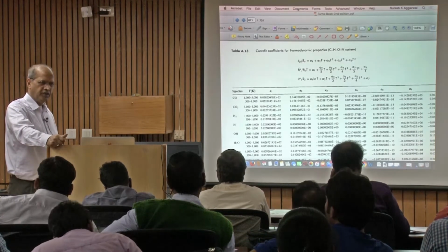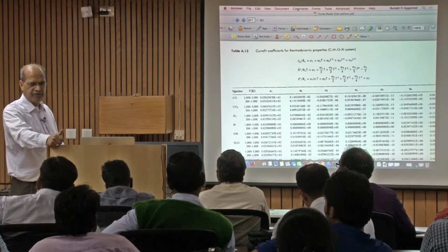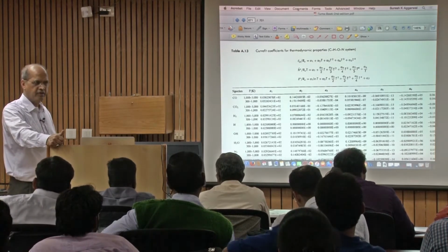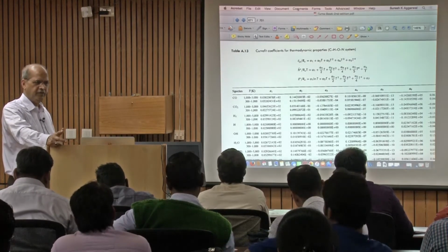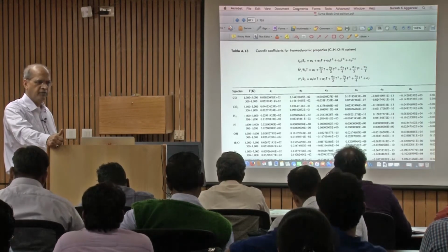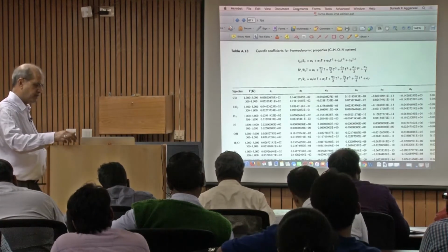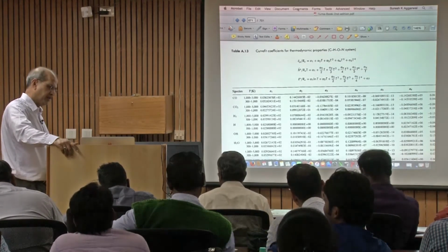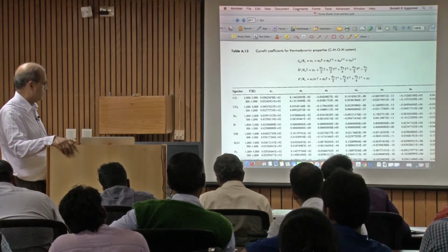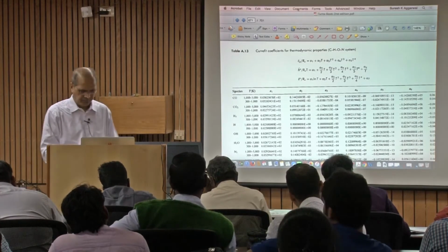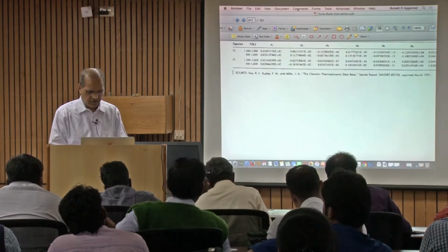For flames, you also need the transport data, like diffusivity as a function of pressure and temperature for different species, viscosity, and thermal conductivity. So you provide 3 files: kinetic file, thermofile, and transport file. If I can find some sample case, I can show you those files later during these lectures. Anyway, this is for the Cp, H, and S.